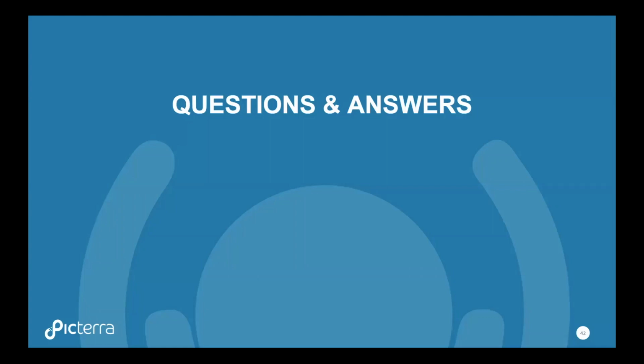So for example, I have a question to Roger. Could you tell us how can we deal with the orthogonalization of building footprints? So this relates a lot to what I talked about earlier. The orthogonalization, or the squaring of buildings, is something that for us needs to happen outside of the model as a post-processing step. And so once you get your detections, they might be a little bit jagged or fuzzy, and then you use geometric operations to square those edges and make them more perfect. And as I just showed you in the platform, currently we have a built-in way of doing this, just to convert your detections to just boxes. However, if you want something a bit more complicated than that, then certainly you can contact us and we can create a solution for you to work on your specific building shape.